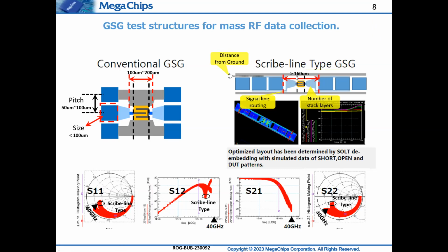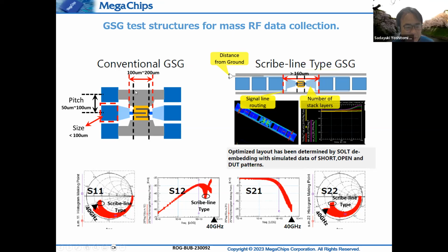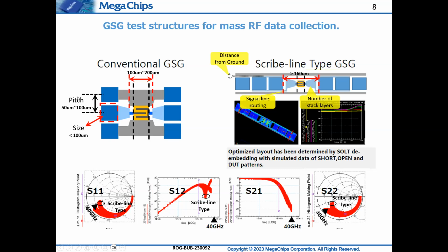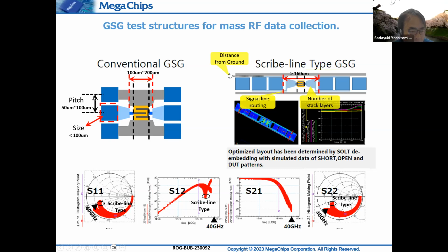The work we did with NIST is around 40 micron from edge to edge. So I'm wondering why is it so large in this case here? Is it because of the probe card or from some physical considerations? Here you mean? Yes. Generally speaking, you are right. We can reduce this size. To be honest, I wrote down the numbers, for example, this pitch. So we can reduce the pitch size down to 50 microns, and the pad size can also be reduced to 40 microns.